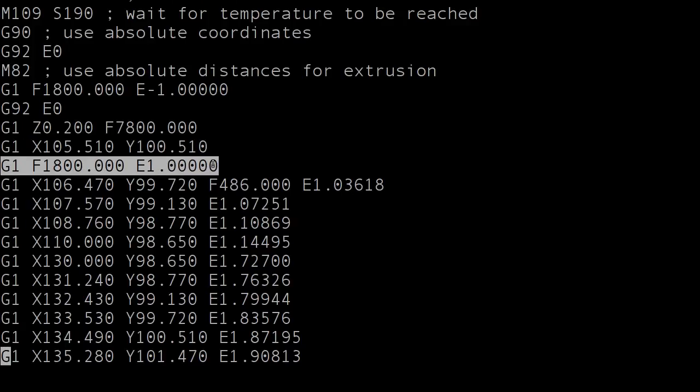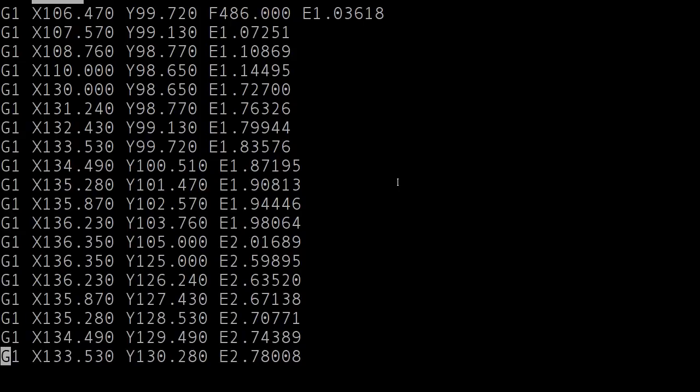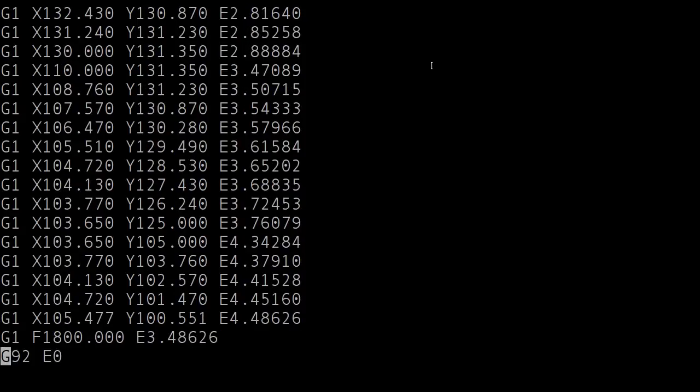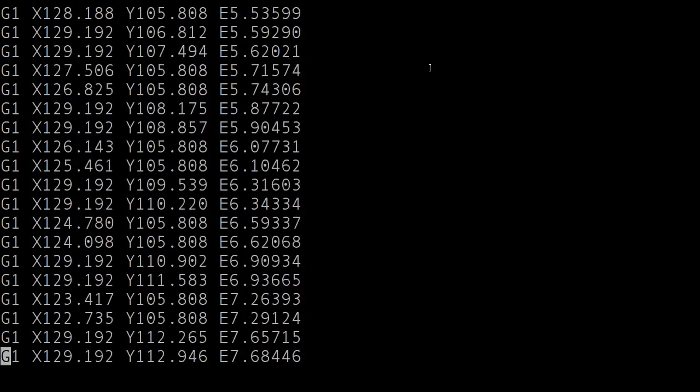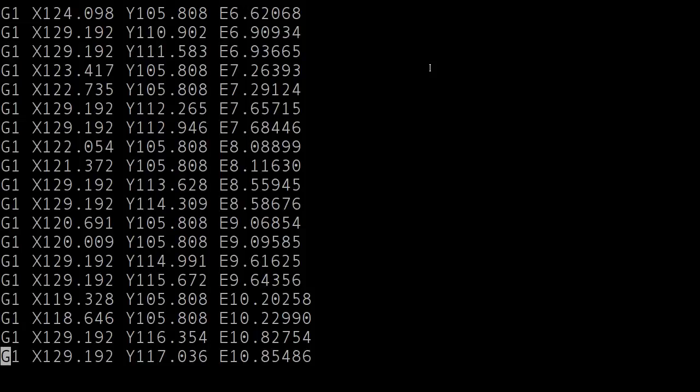We are now going to send a command using the E command to activate the extruder, or actually start spitting plastic out of the nozzle. This is going to be done at 1800 millimeters per minute. This repeats until you have a complete picture. By sending it a series of coordinates, the machine then travels to that coordinate, and with the E command, extrudes plastic as it travels. This is the bare essentials of how the extruding 3D printers work. It does not get any more complicated. This process continues over and over and over again until the first layer is deposited.